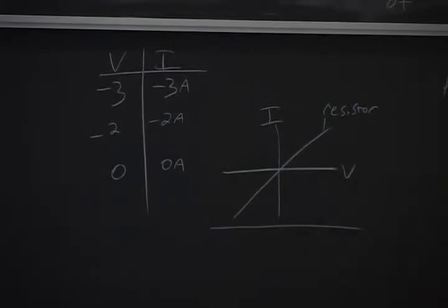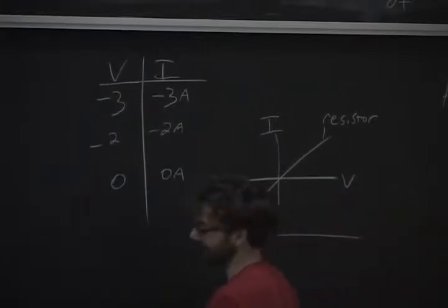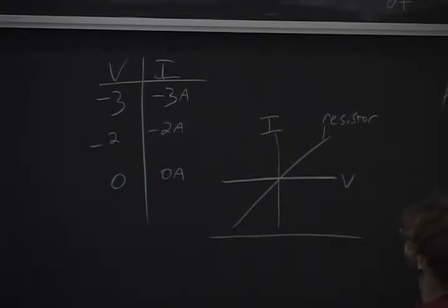If you apply a voltage directly to an inductor, the current's going to change over time. So inductors and capacitors do not have IV characteristics; what they instead have is these differential things, right? So that's just a way to think carefully and critically about what would happen if we actually looked at one of these in the lab.